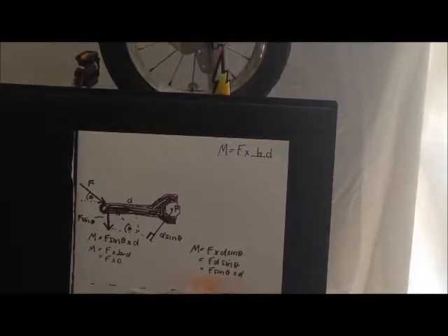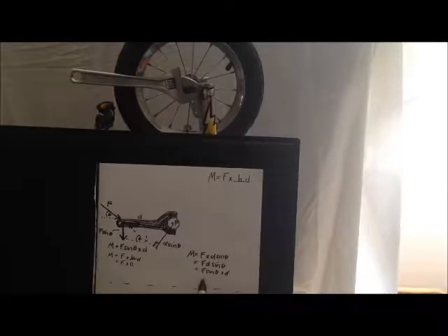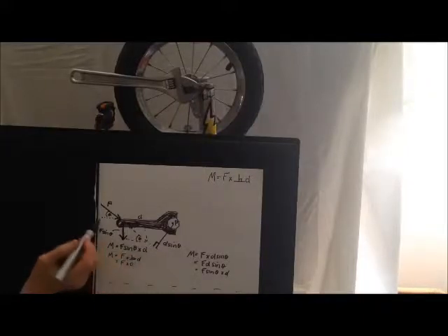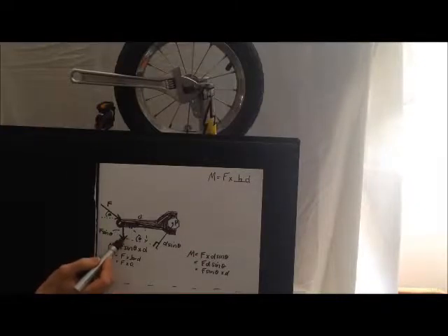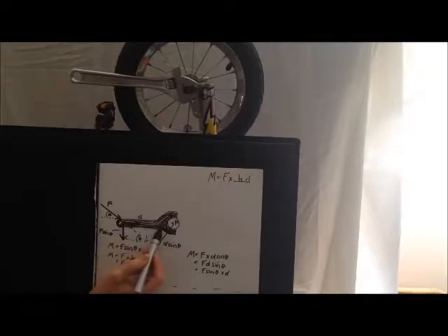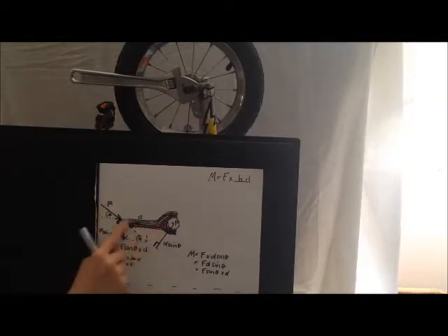So you can see that working out the value this way, using the force times the perpendicular distance back to the point, you get the same value as if you worked it out the other way, where you took the vertical component of the force and then multiplied that by its moment arm back to the point. Because there you used F sine theta times d, and here you use d sine theta times F. So that shows you can work out the moment either way, using the principle that to work out a moment you always have to have a perpendicular arm to the force. A perpendicular moment arm to that force, or a perpendicular moment arm to that force, and you'll get the same strength.